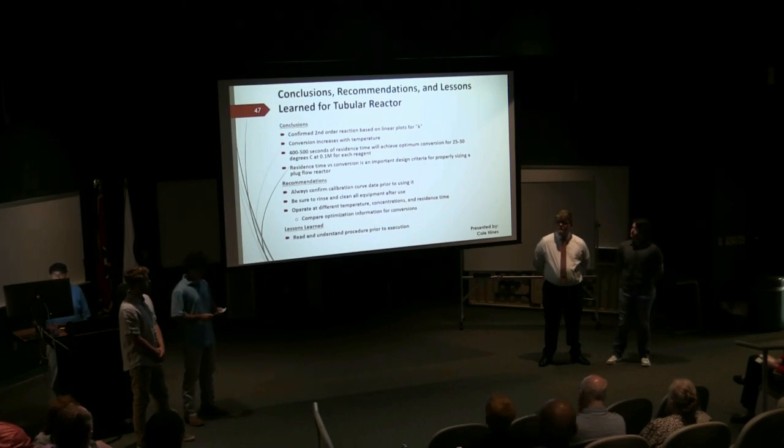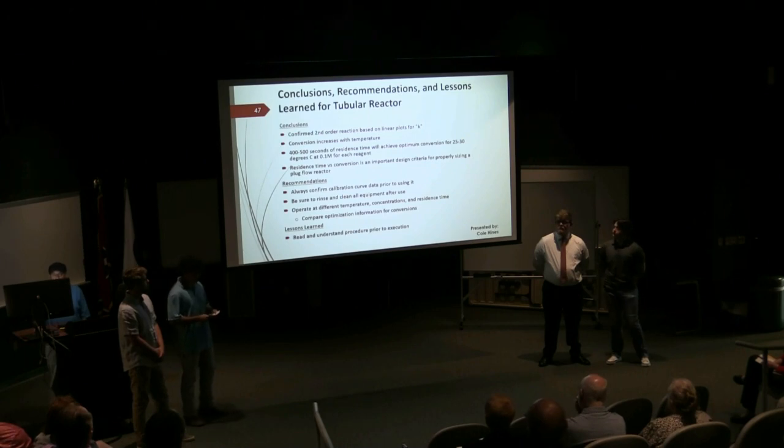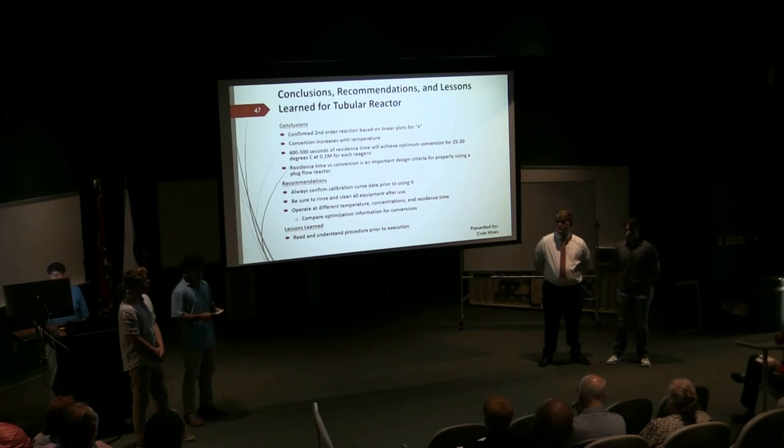Make sure you confirm your calibration curve prior to using the reactor, and rinse and clean equipment after use, and operate at various temperatures, concentrations, and residence time. Make sure to read and understand the procedure prior to use as well.